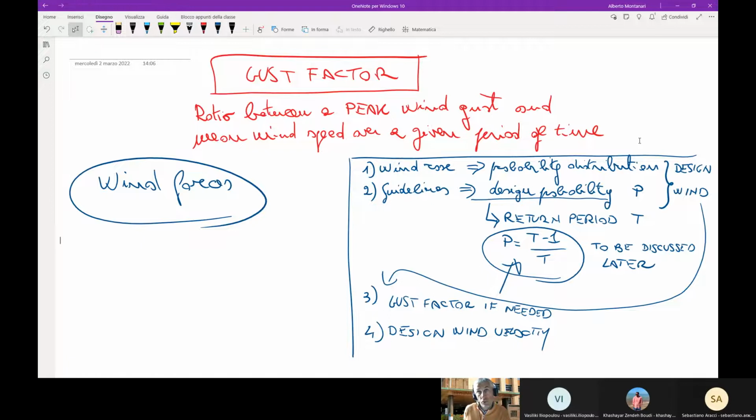When is wind a problem for the berth? When the wind forces become a problem, I give to you another rule of thumb. If force of the wind is up to 4, usually no problem. What is force 4? Force 4 in the Beaufort scale is moderate breeze. Okay. Good.